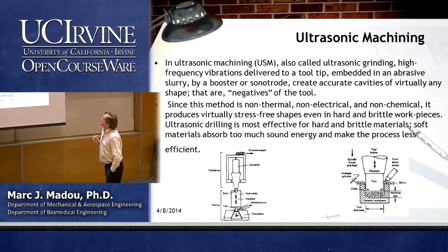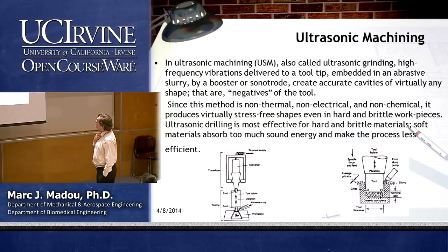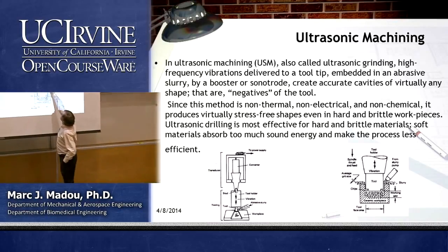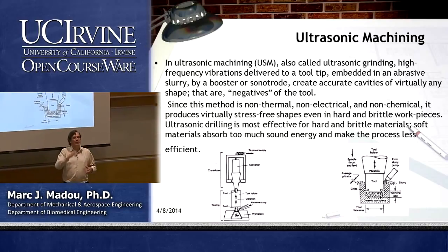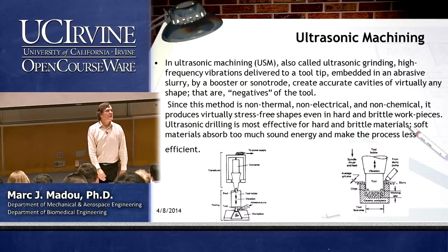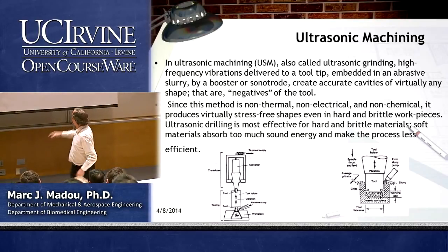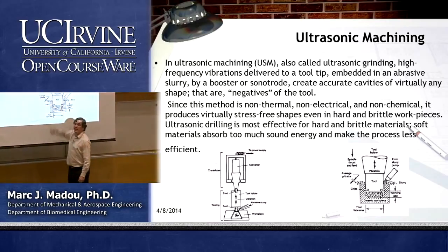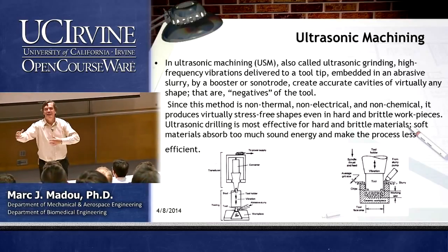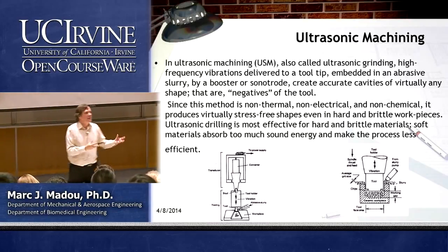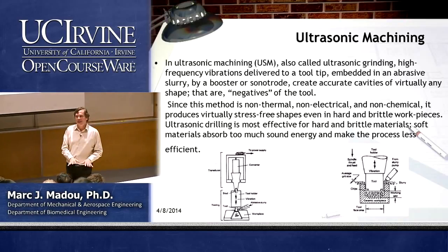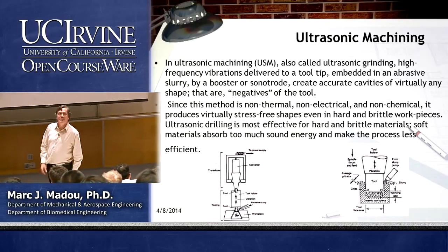So in ultrasonic machining, USM, also called ultrasonic grinding, high frequency vibrations delivered to a tool tip, right? Oh, by the way, does anyone know how we will do this vibration? Piezoelectric. Who remembers what piezoelectricity is? So we're gonna have that tool connected to a piezoelectric structure. Now, what is piezoelectricity? You see, manufacturing combines so many physics, science, materials. People sometimes think it's low art, but it's not. There's a tremendous amount of knowledge in manufacturing.